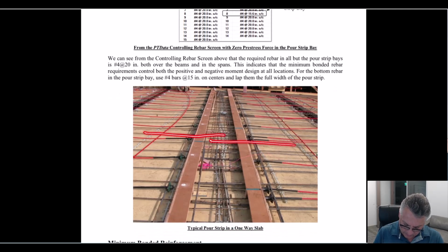So we will lap that steel. We don't want it crossing. We want both sections of concrete, this side to be able to shrink that way and this side to be able to shrink this way. Theoretically, that pour strip will grow in width a little bit. Once that's done or stops moving appreciably, then we fill it in.